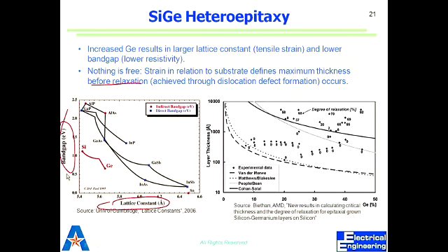So this is now telling us what happens to band gap. Strain heterostructures or strain engineering is also called band gap engineering. Why do we call it band gap engineering? What is band gap? The amount of energy you have to impart to an electron. So for a charge carrier to jump that forbidden zone, we can change that when we do strain engineering. When we have materials in different fractions, we can change the band gap of that combination.